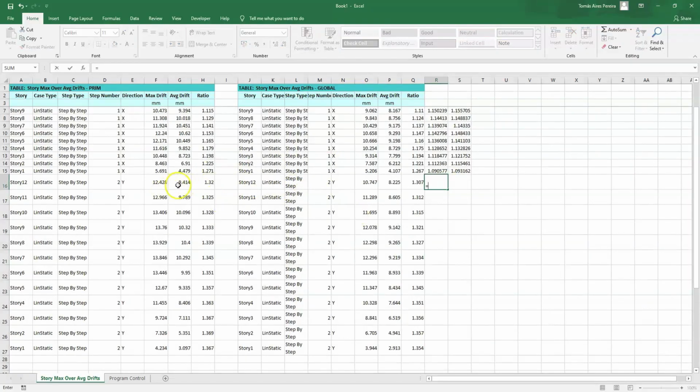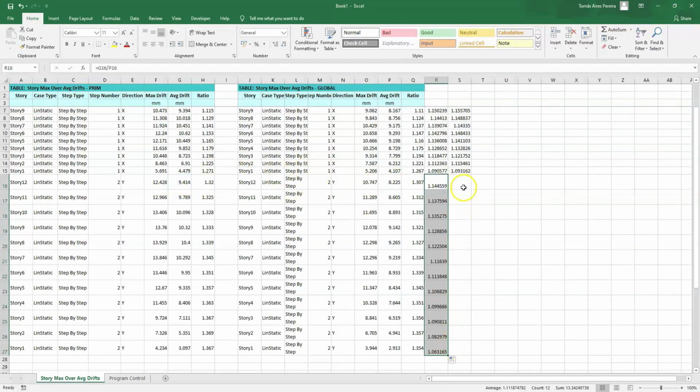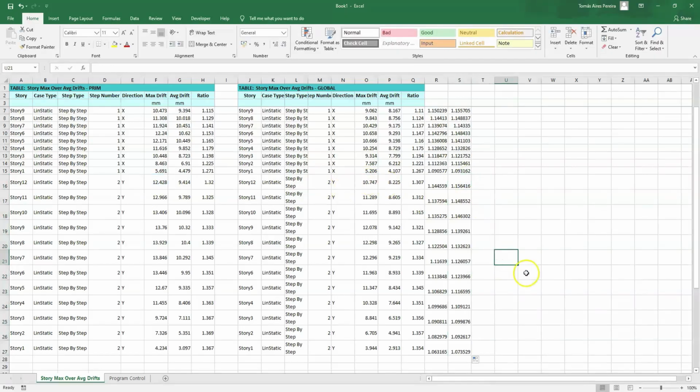In the Y direction, the values are not as severe. Even on the top floor, we are right at the 15% maximum, and generally, the entire building has a secondary element contribution of less than 15%, as we initially hoped.